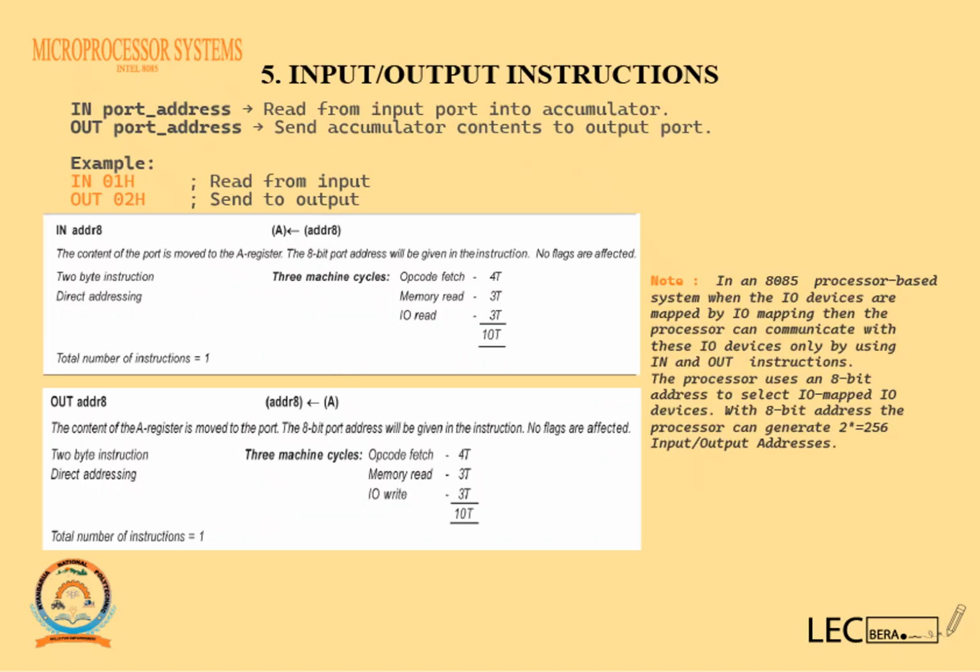So another type of instructions are instructions for reading data from input-output devices. These are called input-output instructions. If I'm reading data from an input device, then I will have to use IN. If I'm writing data to an output device, then I have to use OUT. You remember, input-output devices are going to be interfaced to your microprocessor through what are called ports.